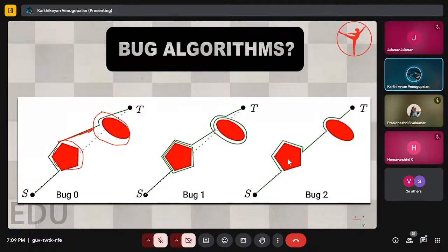Whenever an obstacle is detected, it is going to follow the right wall, as I said, I'm using the right wall implementation here. I will call this imaginary line the M line. Once this M line is seen again, it will turn its orientation towards the termination point and go in this way. And again, if an obstacle is detected, it's going to follow the wall, and once the M line is seen, that's it. We are going to go back to the termination point.